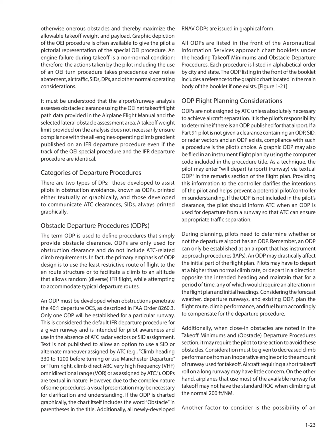It must be understood that the airport/runway analysis assesses obstacle clearance using the OEI net takeoff flight path data provided in the airplane flight manual and the selected lateral obstacle assessment area. A takeoff weight limit provided on the analysis does not necessarily ensure compliance with the all-engines-operating climb gradient published on an IFR departure procedure, even if the track of the OEI special procedure and the IFR departure procedure are identical.